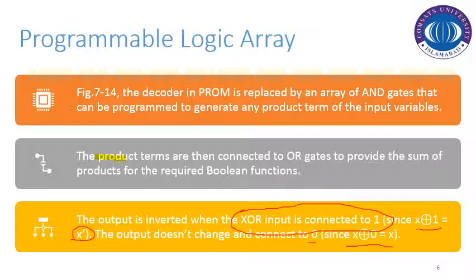So can we also use minterms here? That depends upon the number of resources available. If we've got sufficient resources in the AND array and OR array, we can implement a function in terms of sum of minterms. But due to limited resources, we have to simplify our function and then implement it so that our resources can be optimized.